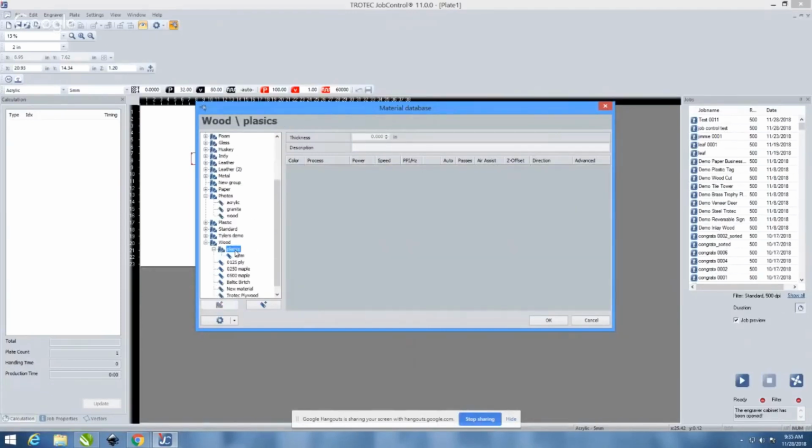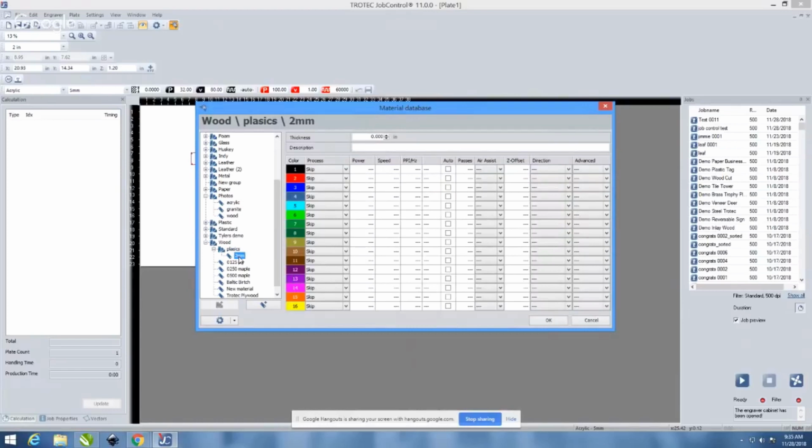So once you have... Yeah, I just want to mention this. It's great if you're doing testing and you have the specific settings. The settings that we provide either in the videos or in the documents on the website are just a starting point. Every material, every laser, we always recommend to test it yourself to get the most optimal results. There is a grayscale matrix that you can download, and there's a whole page on our website that I will post in the description afterwards, that you can use for testing the perfect engraving that you want.